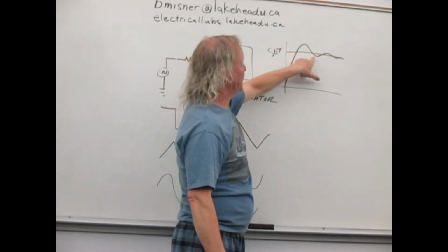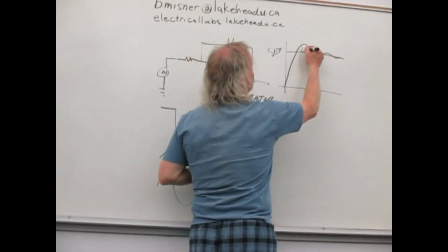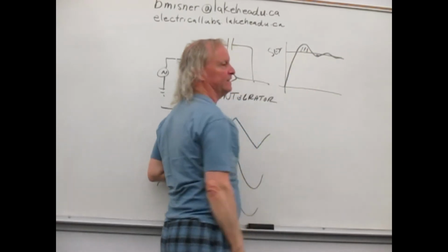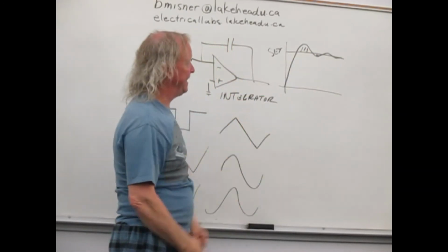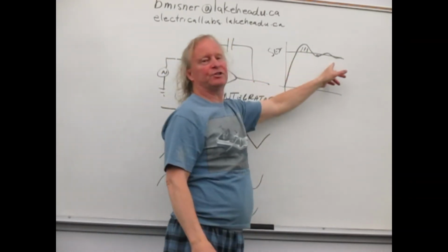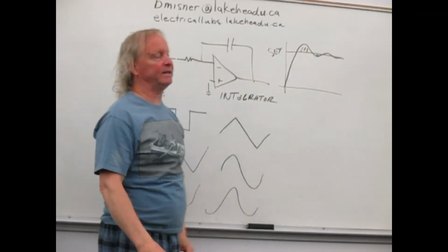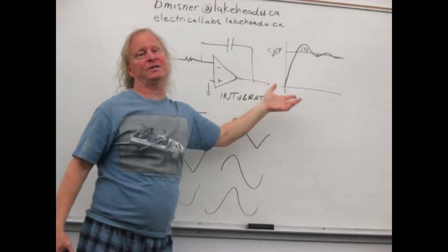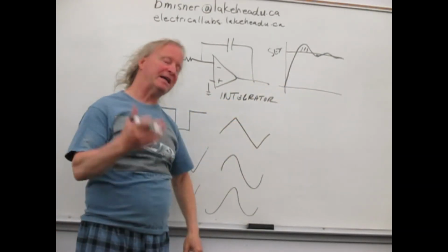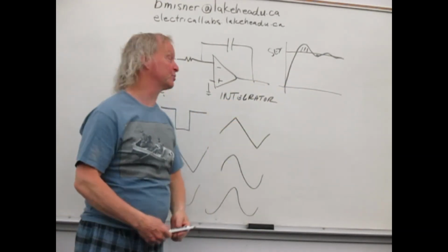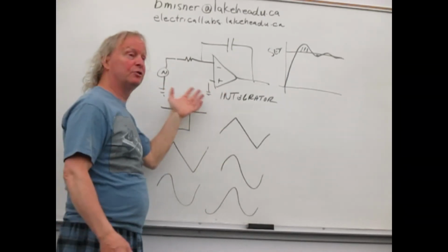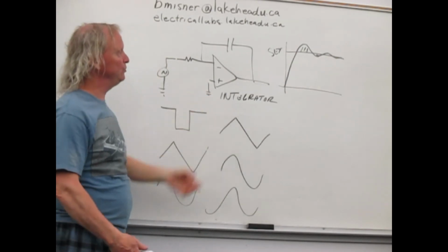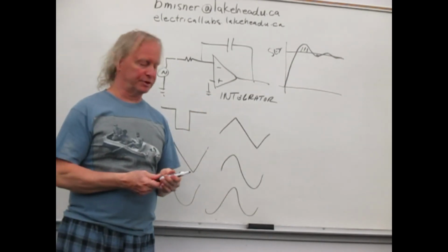And then when you cycle around your set point here, right? Like this one here is supposed to be 1/4 the size of this, right? That's the quarter amplitude decay. And what gets rid of that is your integrator, your area under the curve, right? So again, you're using all of these circuits to come up with a process control. And that's what you're going to be doing in your control systems course. And we do these circuits so you have some idea what you're dealing with when you are tuning these controllers.